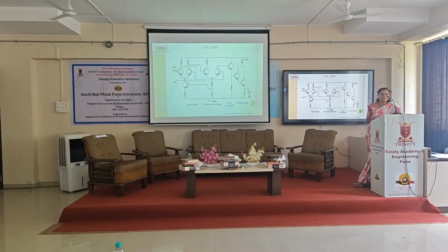That's why at least show the detailed schematic of the IC to the student. The first stage is a differential amplifier, the second is also a differential amplifier, and the use of it is to boost the level of the signal. It provides high gain to the amplifier.